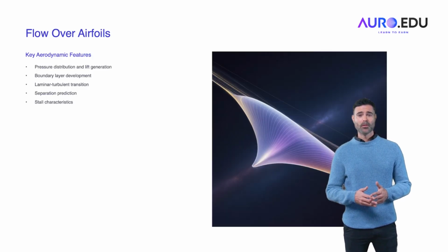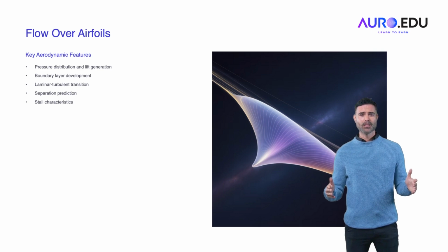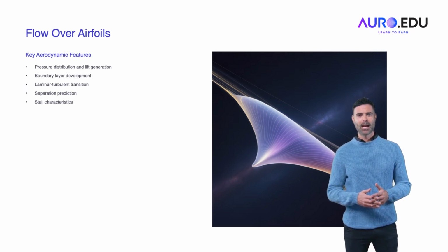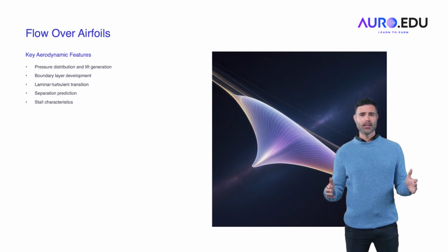Flow over airfoils. Simulating flow over airfoils is a central application of CFD in aerospace. Pressure distribution across the airfoil surface is critical for calculating lift and understanding the aerodynamic characteristics. The boundary layer development on the airfoil surface influences drag and heat transfer. As flow transitions from laminar to turbulent, skin friction increases. Separation occurs when adverse pressure gradients cause the airflow to detach from the surface, leading to drag increase and potential stall.